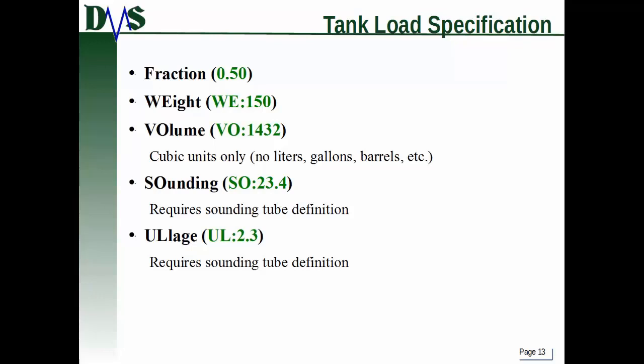Now, let's also match up with what the operator has. Remember, the operators have sounding tubes on these ships that they're checking with a tape measure, basically. It's actually a sounding tape. It's a specialized tape measure. So you can type it in that way, SO, and that stands for sounding. And then you're specifying the actual distance on the tube. So this is the distance that they will read off of their sounding tape. And what a sounding is, is the distance from the bottom of the tank to the surface of the liquid in the tank.